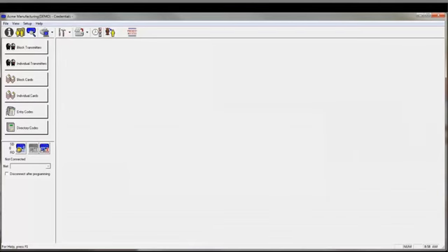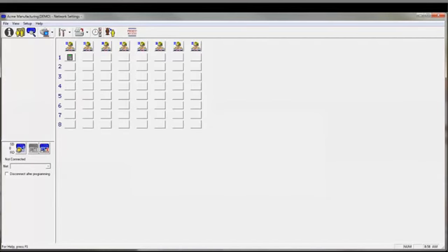Nodes or panels are viewed and configured in the network screen. In this installation, we have one AE1000 Plus in Network A. In AccessBase 2000, we can have 8 nodes networked together via RS-485 communication, and 8 networks, for a total of 64 nodes. These can be the AM3 Plus, AE1000 Plus, or the AE2000 Plus.